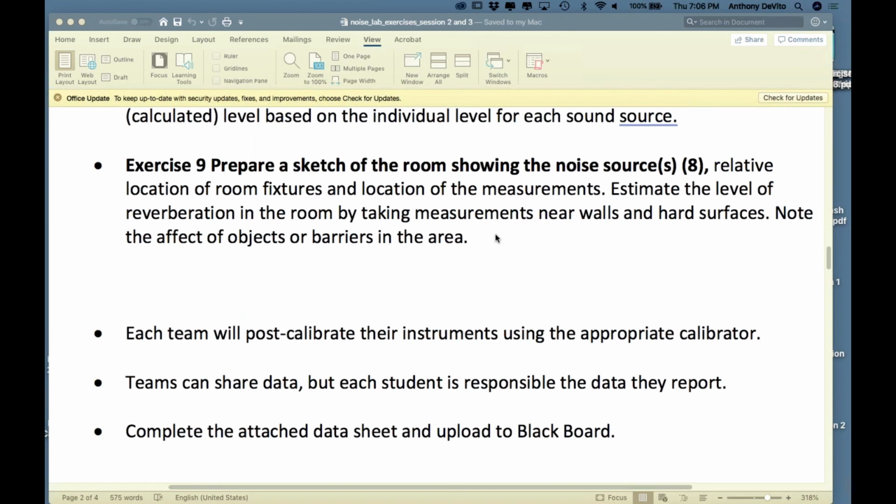What we can do is actually measure. If this is one source here, right here it's 90 decibels. Right here is 90 decibels. Right there is 90 decibels. Over there it's 95 because we're getting sound from there and sound from here. So now we don't get 90. Where is it 80 decibels? Where is it 95 decibels? We can draw lines that show us where we are, that can help us predict how much sound we're exposed to based on where we're standing in the room when those devices are producing noise.